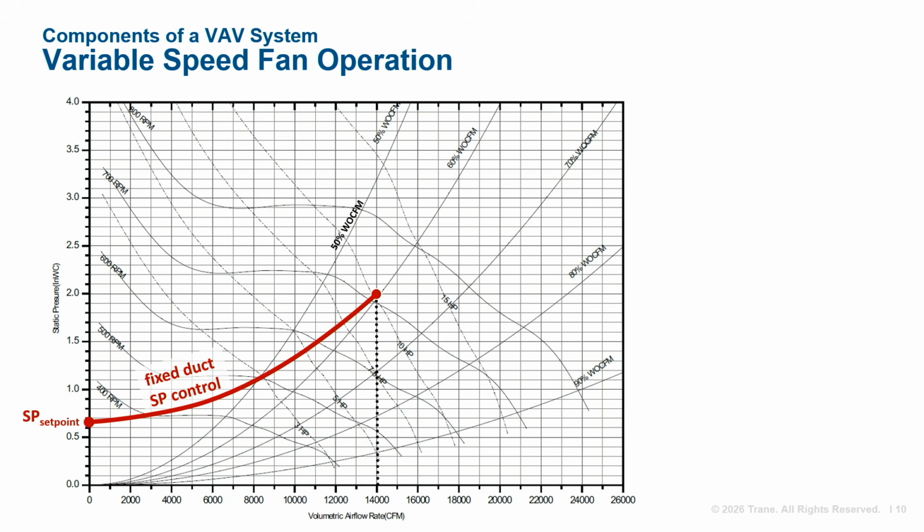This curve terminates at the duct static pressure set point, in this case, 0.65 inches of water. At a part load condition, A, only 9,500 CFM is needed to offset the load, so the fan motor speed can be adjusted downward. This part load point A falls along the system modulation curve, but at lower RPM and static pressure.